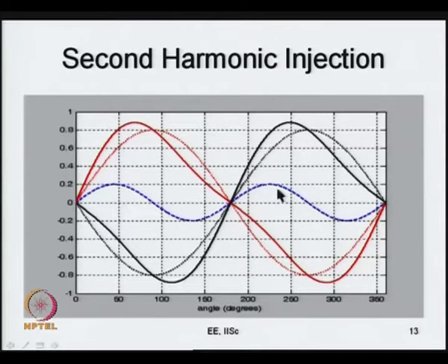So, all I can say is you can add a second harmonic like this of a small amplitude, and you see that the red phase thing increases, the black phase negative peak goes down further. Here again the black phase thing goes further. So, the peak values are going, the modulating signal is no longer quarter wave symmetric. Earlier the sine wave is nicely symmetric about its peak, about 90 degrees, now it is no longer so. So, all this happens, but it is okay, but the final output voltage will be unchanged now.